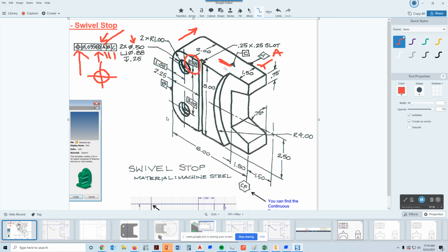So your other question was, could you just go ahead and label what we now have as C, label it as A? Yeah, you could do that. The thing is, a lot of times on parts, A may be referenced by several different holes or something, so in that case, it might preclude you from doing what we're talking about right now. This part's pretty simple because it just has those two holes. So yeah, we could do something like that. Okay, thanks. Sure, that was a good question.